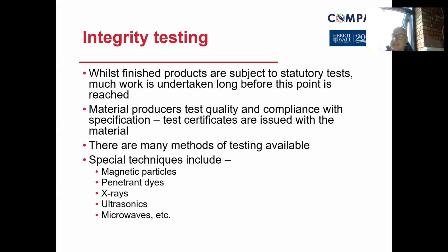If you take a forklift truck as an example, they will also put it under a load test as well. Let's say the forks: one of the weak spots on forks is the heel. As you can imagine, the L shape is the bit where it's bending round. It can stretch and cause a crack if it's under too much load. So if drivers and operators go beyond the safe working load, you're going to get that potential crack growing.